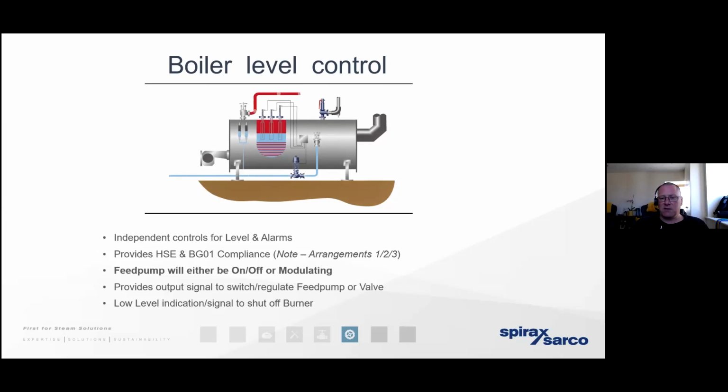But it also means that the boiler's then got to take on more and more energy to get to the point where we can start producing steam. And at that point, the steam that is produced is going to be slightly wet. So we are going to see those erosion, corrosion, water hammer issues. We're going to see steam with less energy contained within it.